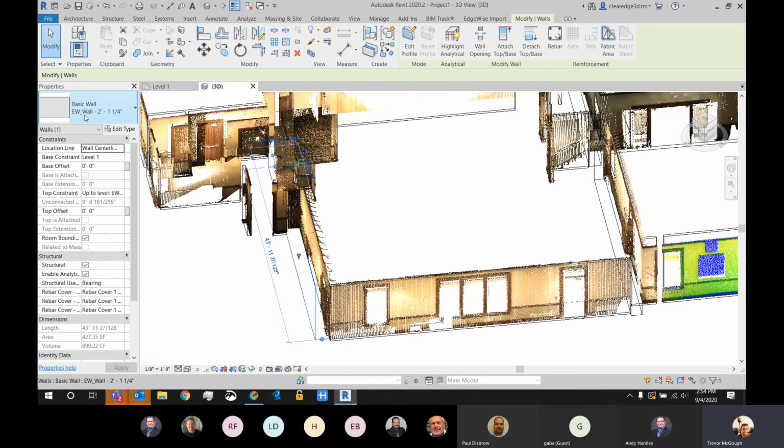In general, I would say going with roughly, for example, the GLS, if you're just scanning in general, using about, I think it's called the detailed resolution or the detailed scan setting, at I think it's like a 6mm at 10m resolution, and setting up maybe once every about 10 feet, maybe 15 feet. That should be plenty for working with EdgeWise. Any other questions about anything anyone's seen today?